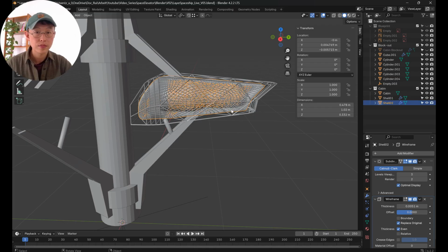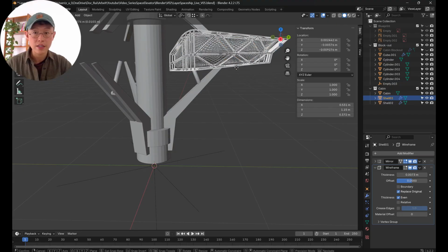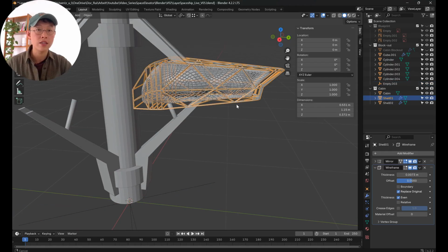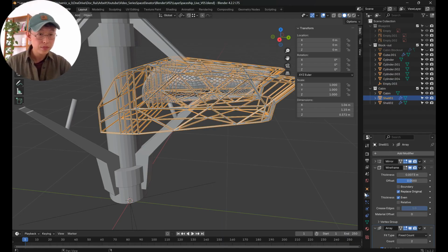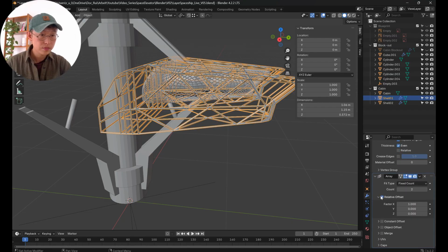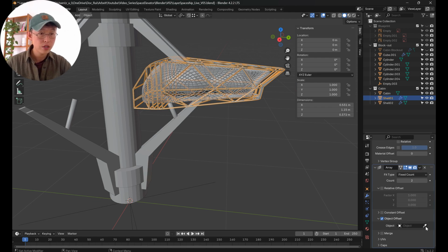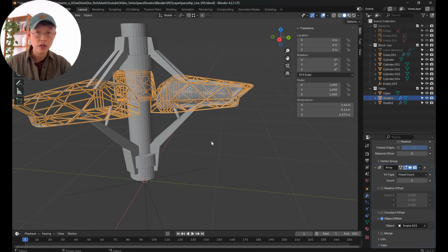All right. And also make sure that the origin is at the spot of the rotation axis. If that's not aligned, something strange is gonna happen with the array modifier. And now, time for array. Object offsets, click on the rotation axis, select the right amount.